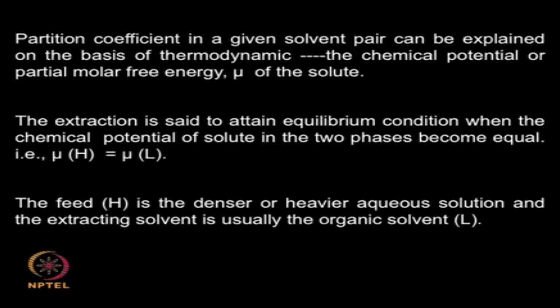Another important point we assume is that, for notational purposes, we generally call the feed the denser or heavier phase and the solvent the lighter phase, but it does not matter; sometimes solvents can be very heavy, like chloroform, but generally we assume this for these sorts of explanation purposes. So in a thermodynamic situation the chemical potentials are equal, that means the system has reached equilibrium.